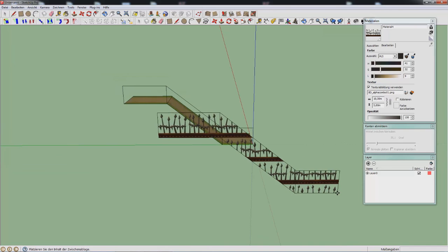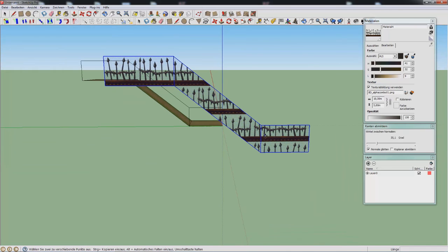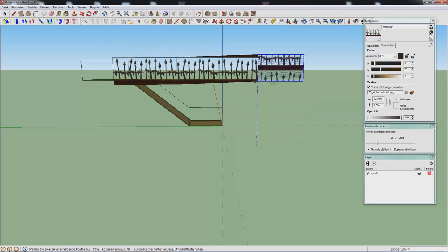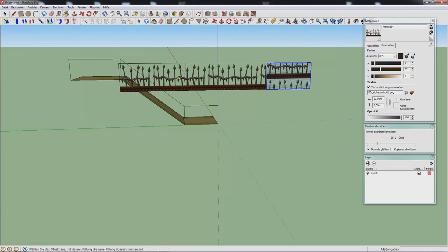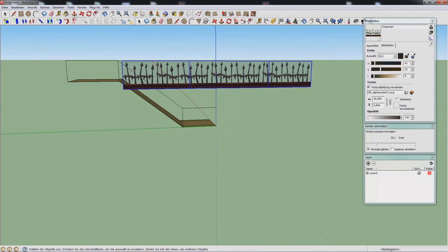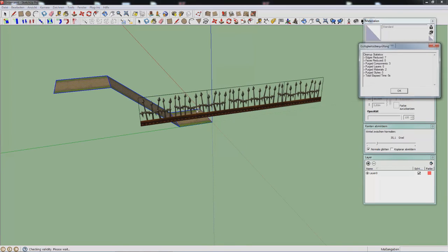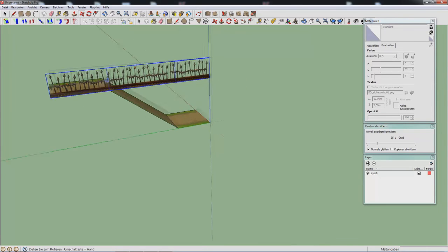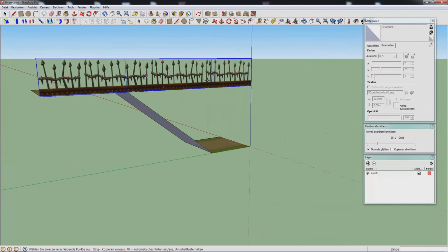So we just take all this, move it into one line, like so. Copy this texture, put it here, copy this, put it here. Then you are going to make it a component. It's the easiest way. Also saves faces sometimes. I just find it less annoying to do it in a component.